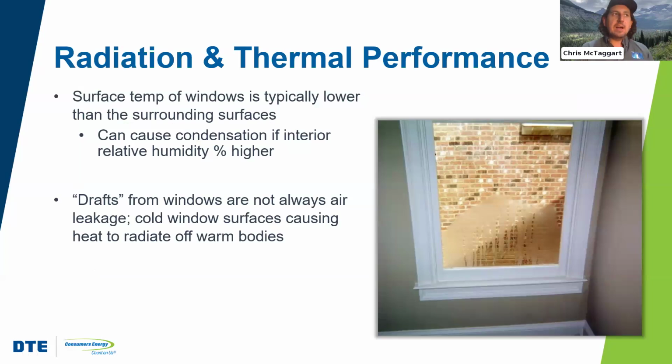So if we go back to that colorful image that showed the potential heat loss off of different configurations of a double pane window, we saw that some of them had an indoor temperature of like 40 degrees. Well, guess what? That's going to feel like a draft. It's going to be sucking heat off of our bodies being close to a cold window like that. The feeling of draftiness near a window is usually through radiation, heat being sucked off of our bodies rather than air blowing. Could be a combination of both.